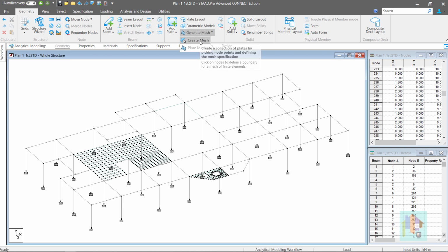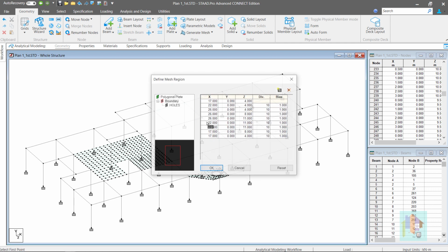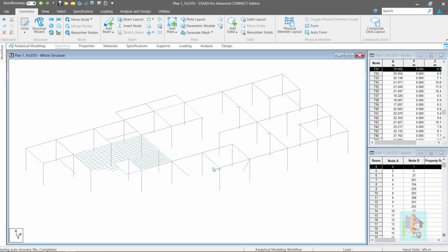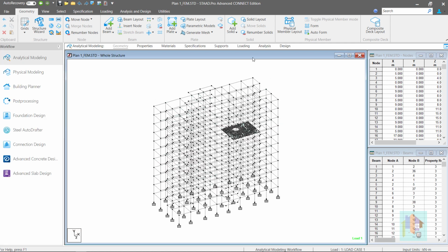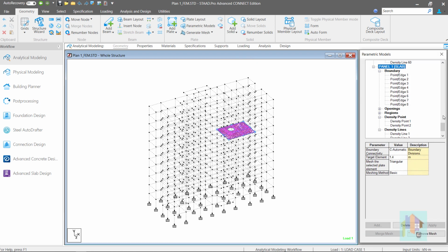This mesh generation technique is useful for regular panels, but for irregular panels, it is a lengthy process as we need to generate a plate mesh for each panel separately, maintaining proper boundary division and connectivity. Not suitable for this structure. There is another option which I think is the best solution to generate any plate mesh.